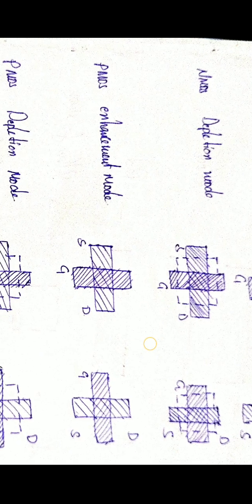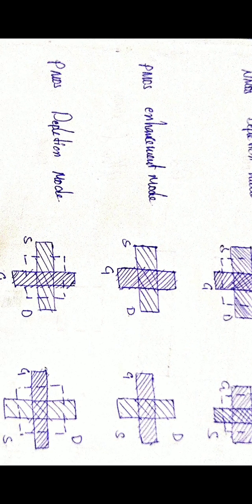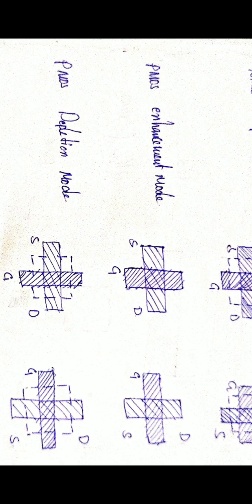Whereas for a PMOS transistor, we will use P diffusion and polysilicon. The polysilicon is used for the gate and P diffusion is used for source and drain. Similar to the NMOS transistor, in a PMOS transistor also we can draw P diffusion horizontally and polysilicon vertically, and vice versa, depending upon our requirement. The P diffusion is similar to the N diffusion, but we will maintain some space between line to line in the case of P diffusion. Similarly, we will draw the polysilicon also.